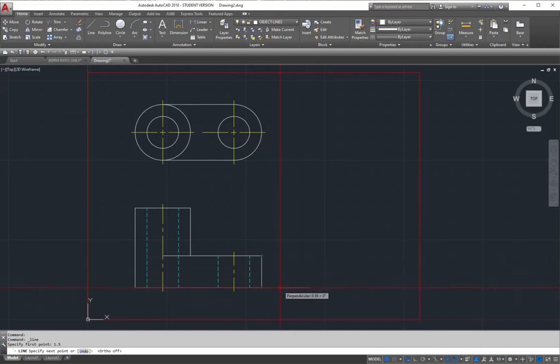They both share the same front end point, in the front view or the left or right side view. So if I want to make a line that length, I can simply go up in this direction, this distance, and go again. Don't click on anything, just place your cursor there and slowly move it. When you see that broken line, you'll see that eventually it will create right here a 90-degree angle, and that is the distance of my line.